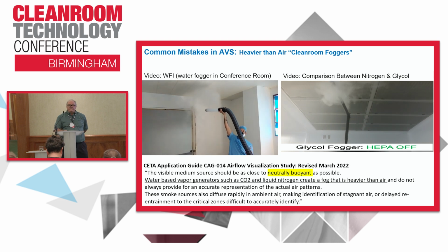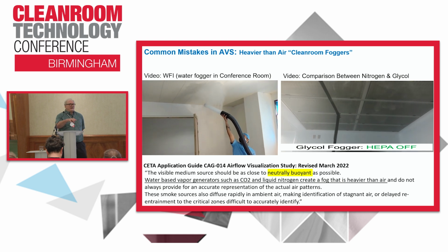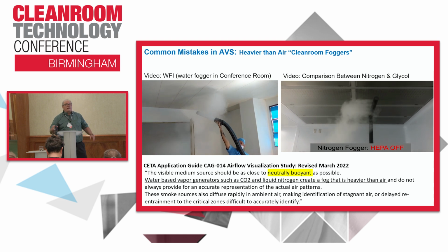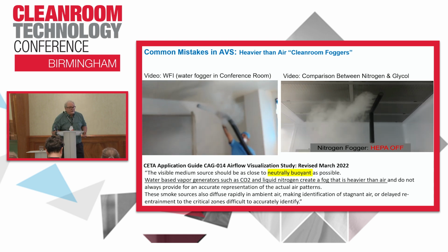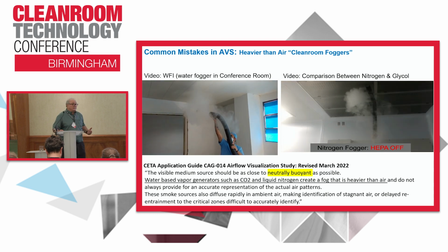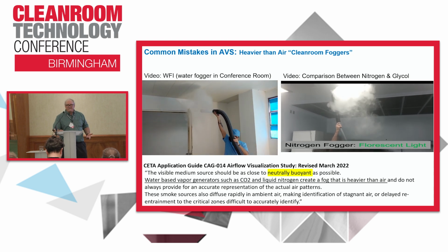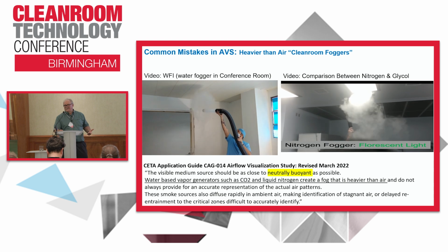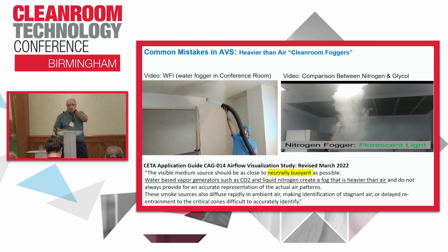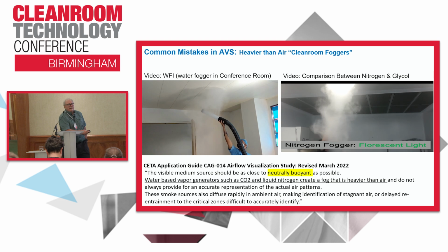You're not going to assemble your filler, do a smoke study, and start production. You're going to assemble your filler, do a smoke study, simulate filling and closing operations, running water into vials, putting stoppers in, right? Simulating broken glass, simulating jams, simulating cleanup, and then you're going to break the machine down and sanitize and sterilize all the components. It's not a quick test. If you're going to do a comprehensive smoke study, it's not a simple test. You have to plan on it. And it's not going to be clean. You have to disassemble the equipment anyhow.